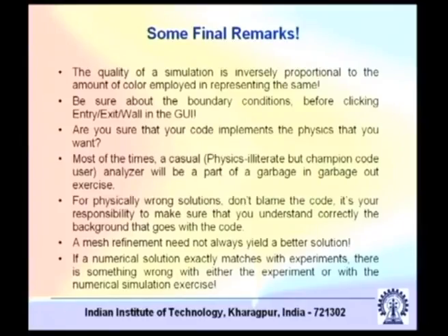The reason is you cannot perfectly match an experimental condition, which is a reality, with an idealized condition where you do not actually know the boundary conditions. You say something is isothermal, but that is not really isothermal. Then you specify certain properties, but you really do not know how those properties vary with temperature and other conditions.